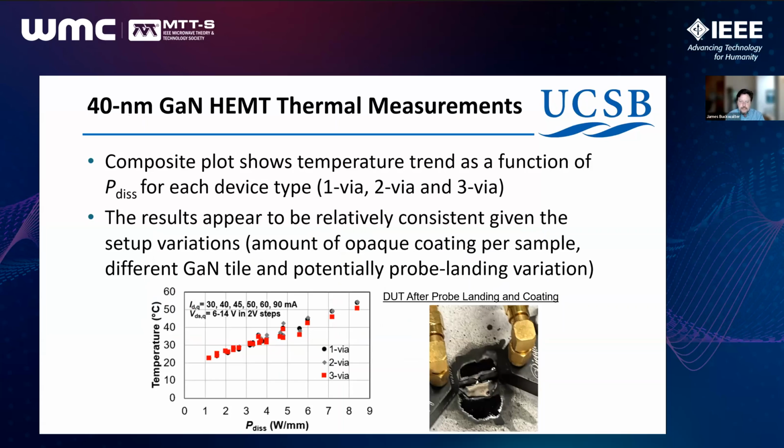And so we went and did this experiment where we measured the temperature with an infrared camera on the device under these different conditions. This is a picture of the setup. We had to apply a black body around the transistor so that the infrared camera would pick up the most contrast. And you can see what we ended up doing was sweeping the dissipated power through the device and measuring the change in the camera temperature.